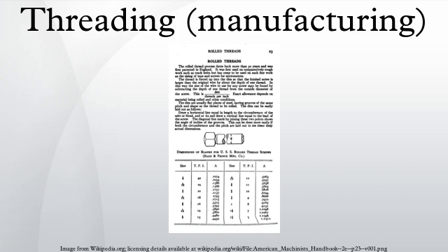All threading could feasibly be done using a single-point tool, but because of the high speed and thus low unit cost of other methods, single-point threading is usually only used when other factors of the manufacturing process happen to favor it. Thread milling. Threads may be milled with a rotating milling cutter if the correct helical toolpath can be arranged.